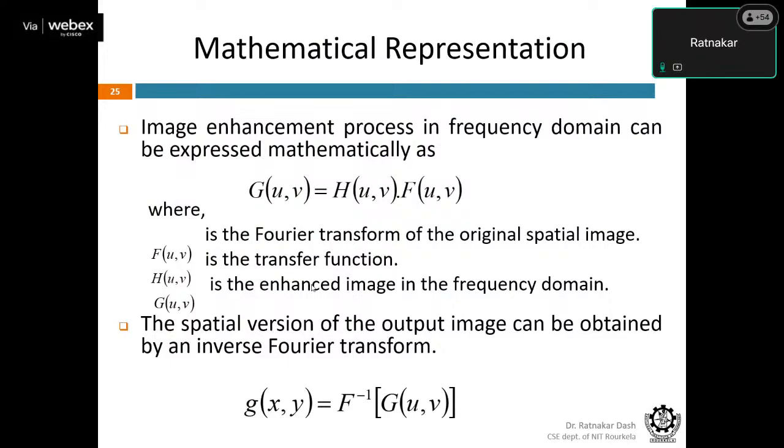There is a very good property that exists in convolution. It says that when you apply the convolution operation in the spatial domain, the same operation can be achieved in the frequency domain with a simple multiplication. So if I replace this equation, all notations are in small caps, I can write g(x,y) equal to h(x,y) convolved with f(x,y).